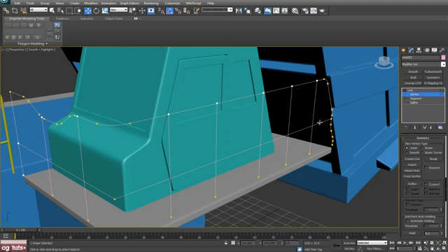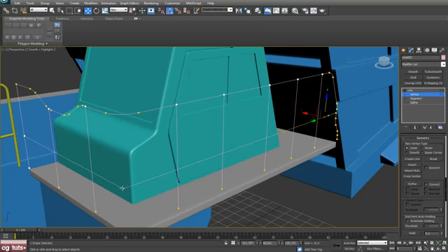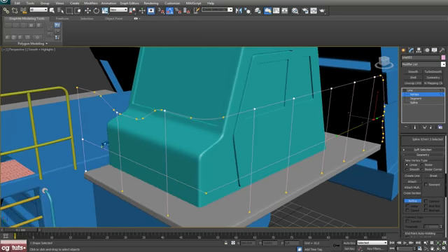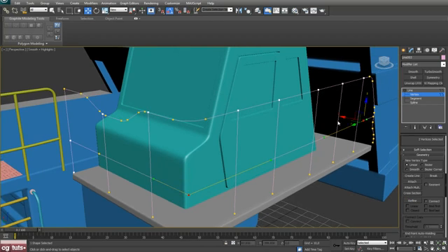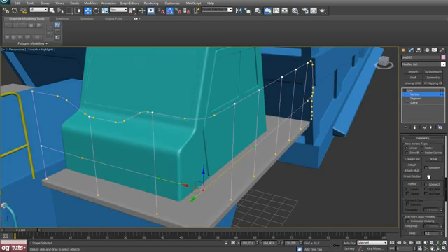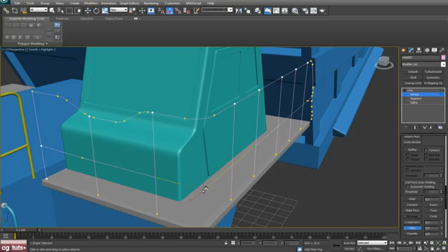Okay. And select her now, and this actually we need one more vert here. Select, make one vert here. Okay. Now select these two verts and push them out just a bit, and now select this one and push them also out just a bit, and now select that one, make one fillet.